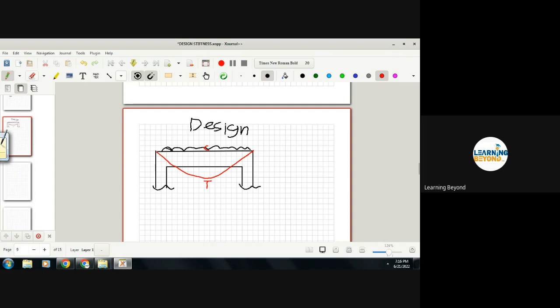So there is a bending moment M, and there will be shear force also. All of you know the shear force will be there also, something like this. So you see that there is a maximum shear force near the support. So due to the moments and shear force, there will be stresses within the beam.